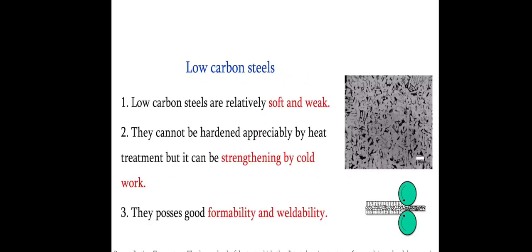Low carbon steels are relatively soft and weak. They cannot be hardened appreciably by heat treatment, but they can be strengthened by cold working. They possess good formability and weldability.